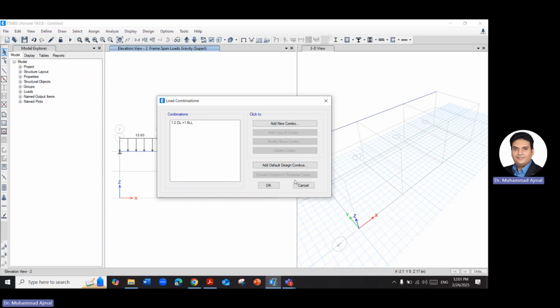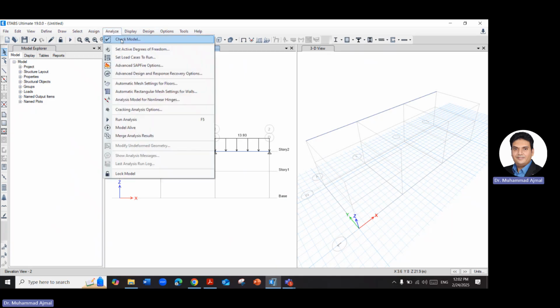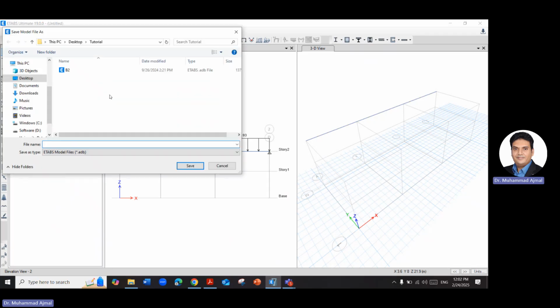For the timing, we will come to the live load later on because the time is already finished. I will just run the analysis to show you the dead load answer, okay? Once you apply this load, you have to apply live load also the same way. I will go to run analysis. You will find a play button there, or you can go to analyze and run from here, okay? When you click on run, it will ask you to save your beam.